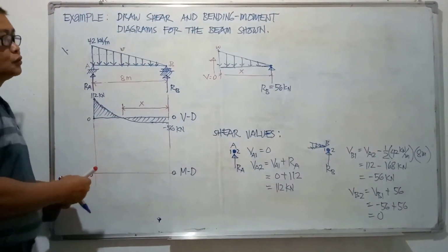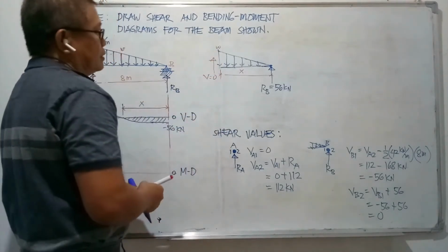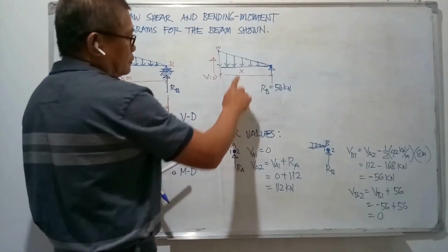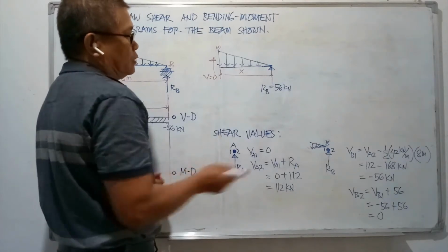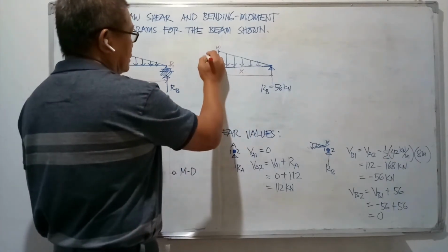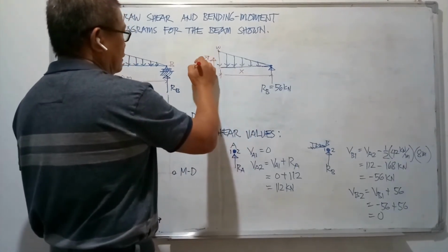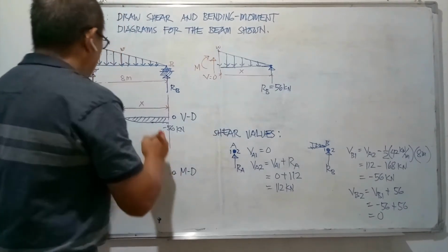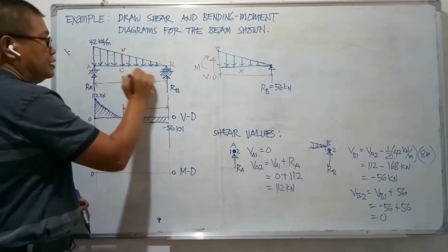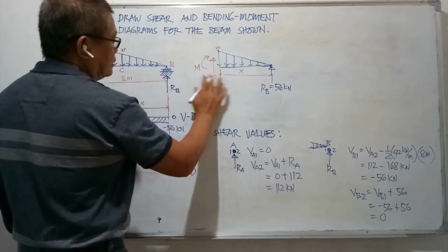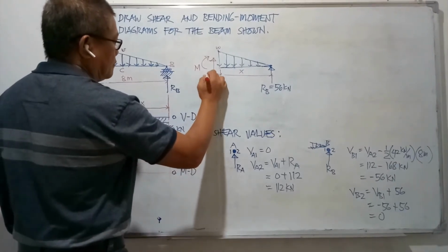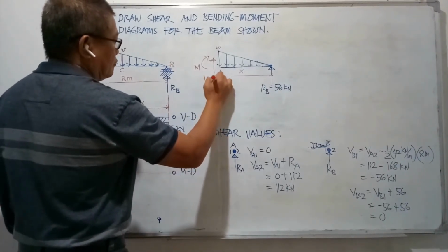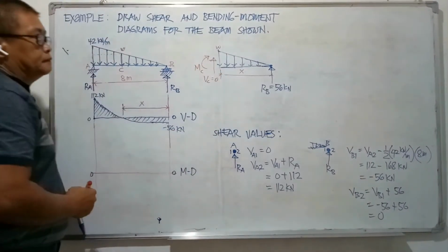And if we have to solve for that shear, then it will be a function of x, and we can solve for x. We actually have also a moment. So if we designate this as point C, this is V sub C. This one is M sub C.